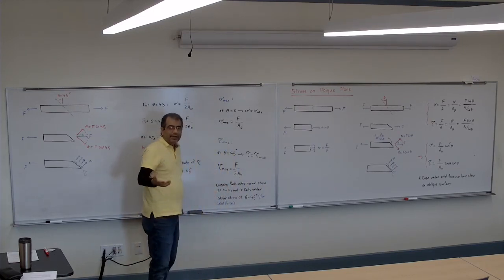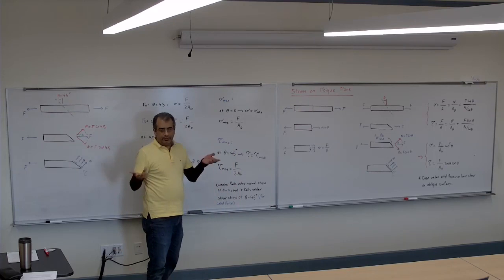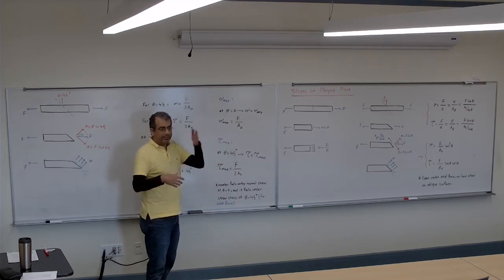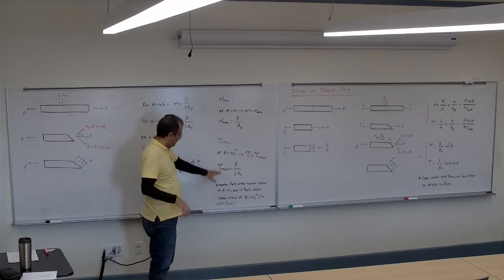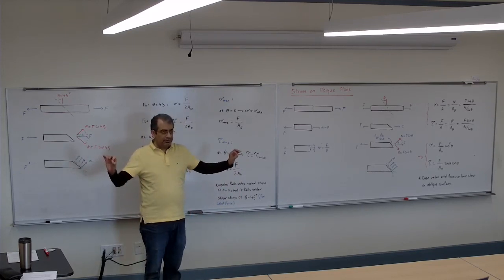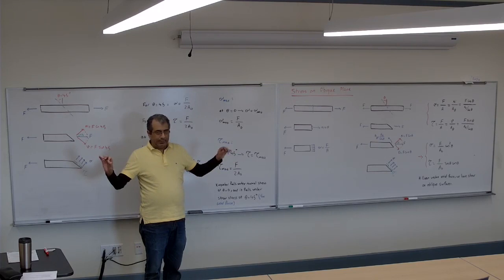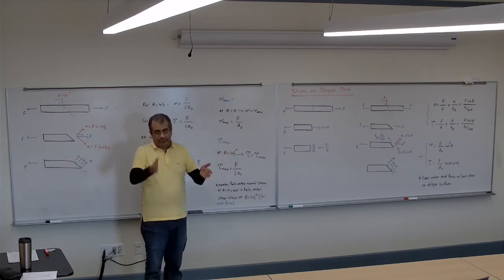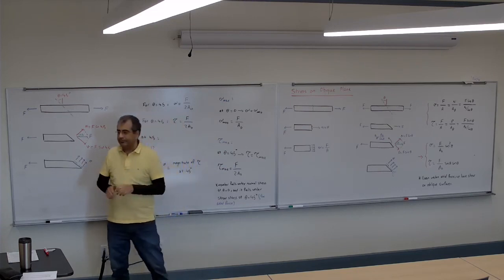If we have other types of force, if you have bending, and we have shear and we have torsion, that's not correct. If we have the pure axial force, it only breaks under the normal when the theta is 0, and under the shear when the theta is 45 degrees.